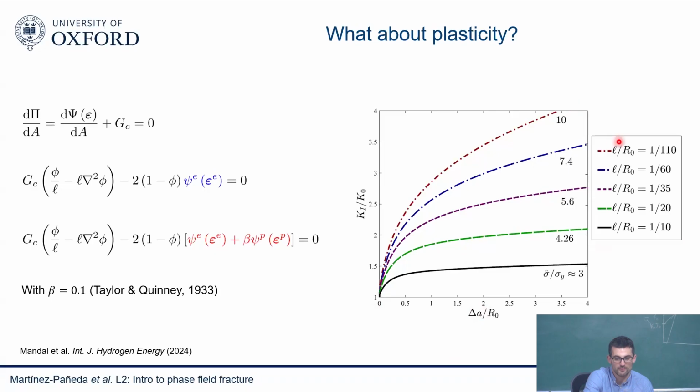So you see here, if I take different values of L, I'm considering different values of strength. Here they are plotted relative to the yield stress. And I'm not going to get into the details of the simulation. This was with strain gradient plasticity, it doesn't matter. But what you see is that basically, no matter what value of the length scale you take, fracture initiates at the same point, when the energy is big enough to reach a critical point. This is an example with a big crack.